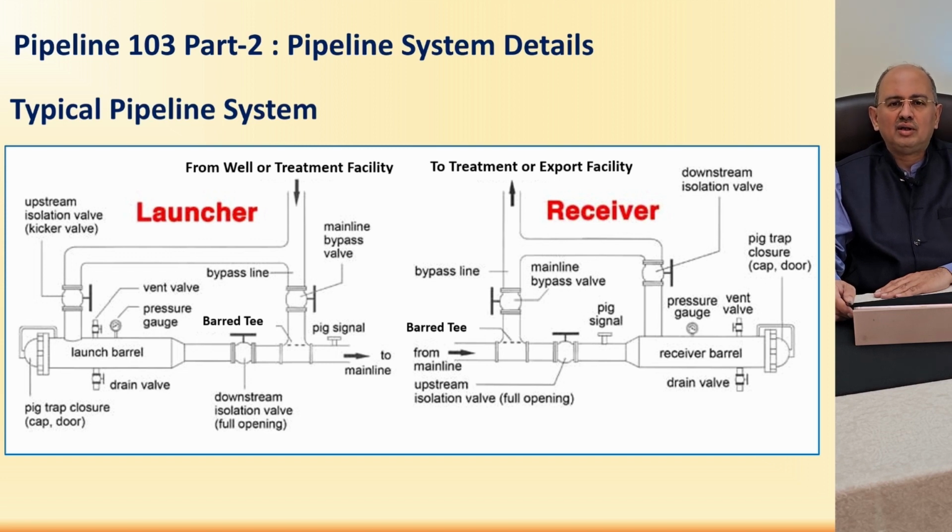And also the pigging, or scraper. You can imagine a piece of metal with brushes or wires connected to it, which is passed through the pipeline, and it will clear all such deposits, and it will also push all the liquid which is getting stagnant at the low points to the other end of the pipeline. So this is called pigging, and it is basically cleaning the pipeline in a way, indirectly.